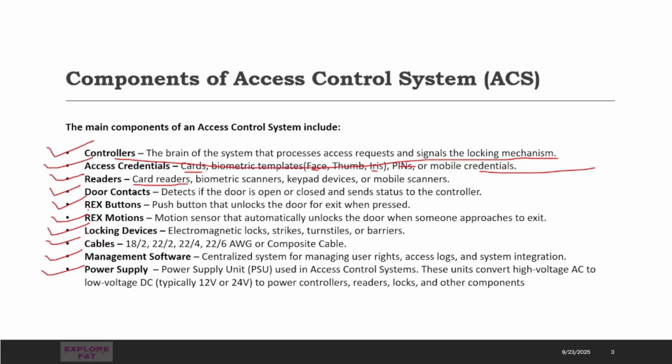REX means request to exit. The REX button is just a push button. These are installed inside the secure area, not outside. Outside, only the reader will be there.